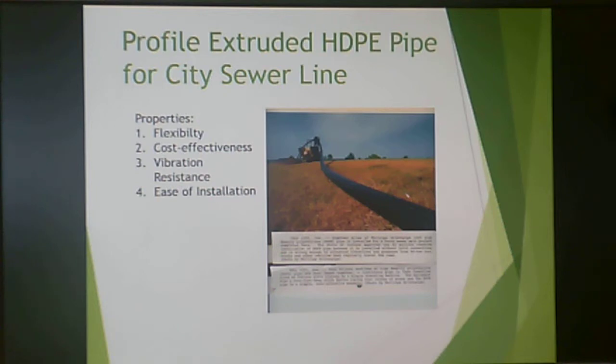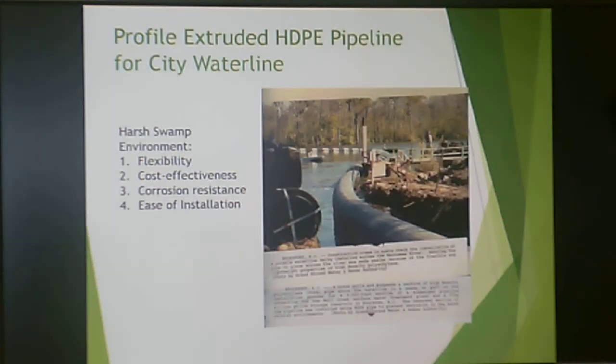PEX is a little bit different. When you talk about PEX piping for homes, that is cross-linked polyethylene, but that piping for homes is also superior to, say, copper or especially the old cast iron pipes. Polyvinyl chloride has a lot of application as well, but PEX is very flexible. So piping made out of HDPE or cross-linked polyethylene is getting a lot more attention for household piping as well.